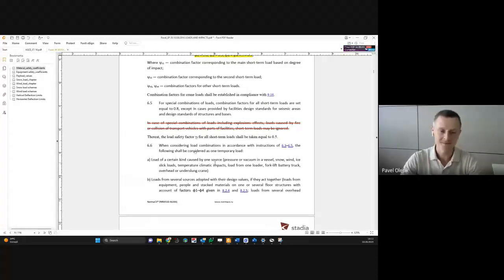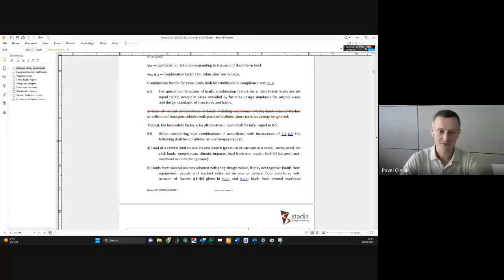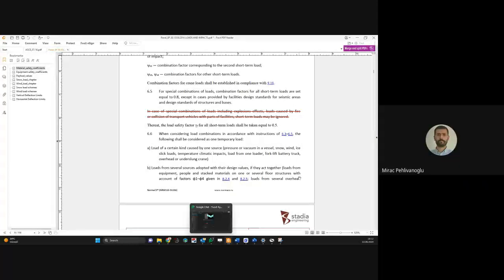You are right, snow cases are usual combinations, as usual snow. Snow consists of different types of snow, with a single case when mu is 1, and maybe some specific cases such as with these trusses, when we have half snow and no snow on the other half of the truss. That's it. Thank you. You're welcome.